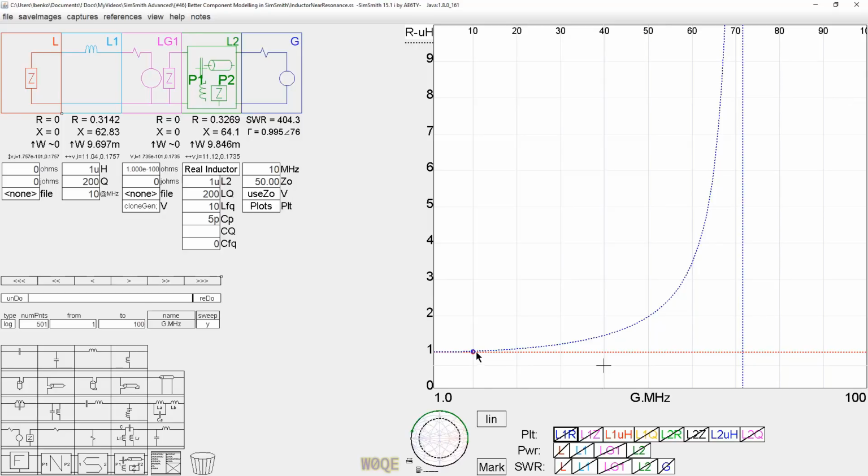As we saw in our example on that inductor previously, there was a slight increase in inductance due to the capacitance. Now, this resonant frequency, I believe, is 71.2 megahertz or something like that. If we go to say 1/3 of that, so 71 divided by 3, about 23, 24 megahertz.